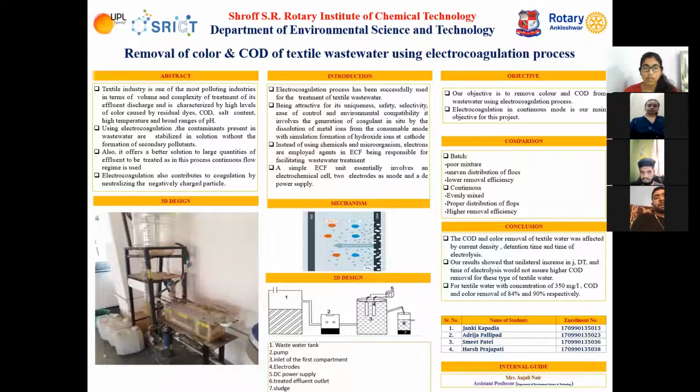Thank you, Janki. Now, the issues in textile industries. The textile industry is one of the most polluting industries in terms of volume and complexity of treatment of its effluent discharge, and is characterized by high levels of color caused by residual dyes, COD, salt content, high temperature, and broad ranges of pH. Using electrocoagulation, the contaminants present in wastewater are stabilized in solution without the formation of secondary pollutants. Also, it offers a better solution for large quantities of effluent to be treated, as in this process a continuous flow regime is used.